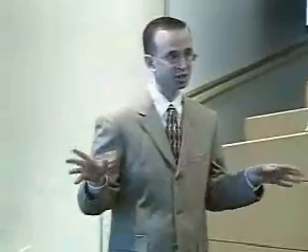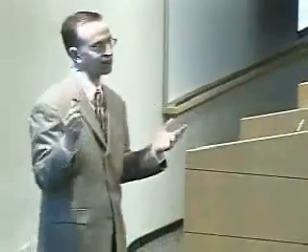I'm not a graphics guy either, but I can answer. Basically, I view these as being from least accurate to most accurate, the least accurate being just the model approach. You don't consider the environment, just large-scale path loss and statistical fading. The next step above that is a ray trace. We're cutting corners, but still we've got some multipath information that we don't have in the other approach. If you look at Toy Story, it looks similar to a real house if you got down to that level. So you could get something that looks pretty good from an RF standpoint, but wouldn't be perfect. And then the next approach would be to go out in the real world and record, ideally with the channel sounders. That's how you're going to get as close to reality as possible. There's always going to be some error anytime you measure something, of course.